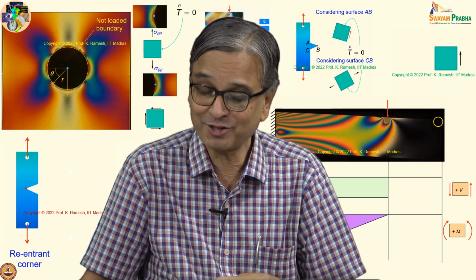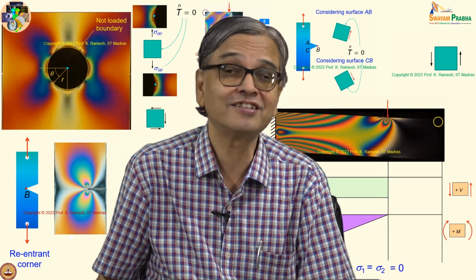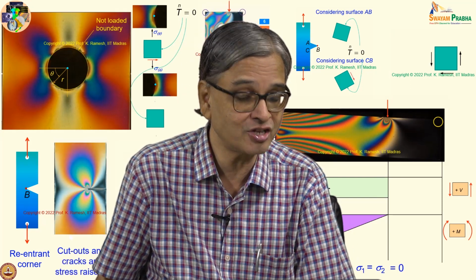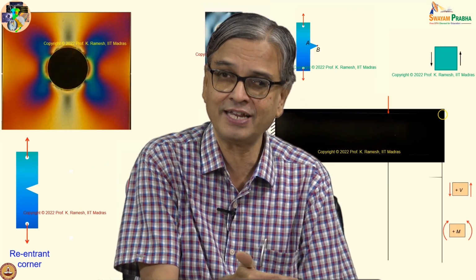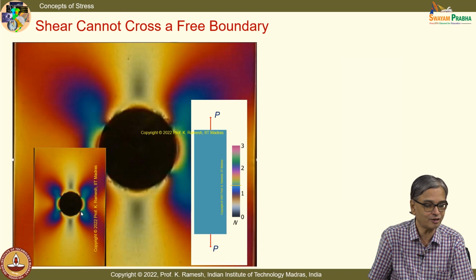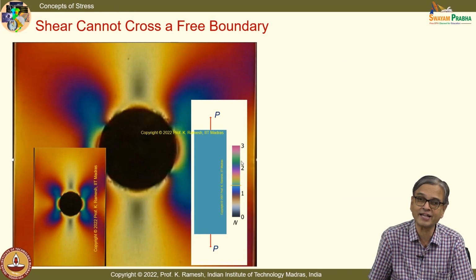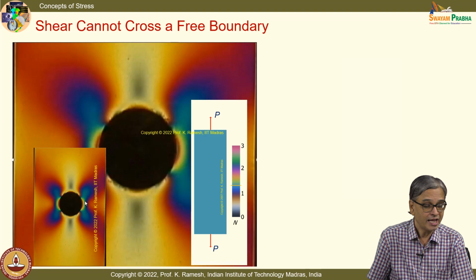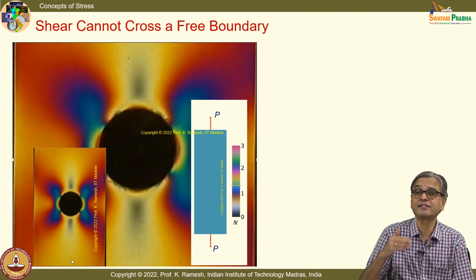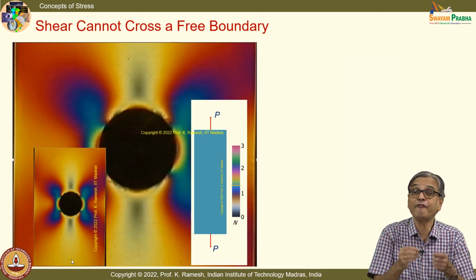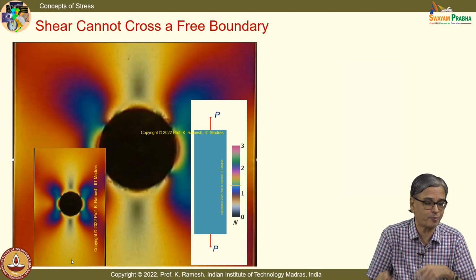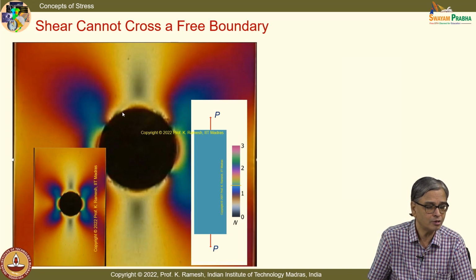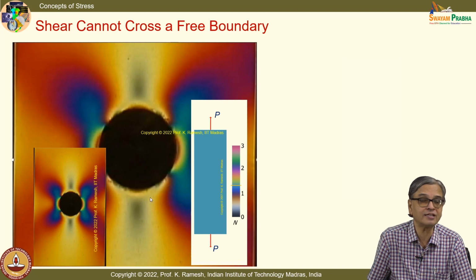It took sufficient discussion to appreciate that the presence of a hole introduces a concentration of stress, which you can see very clearly. I have the color code. The color code says that this is a very high number, and this turns out to be 3 times the P by A for an infinite plate with a small hole. If I have to go and solve that problem, I should know how to specify the boundary condition on this inner boundary.